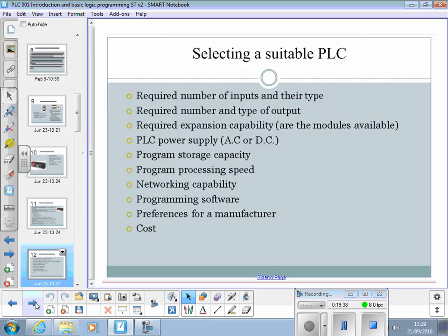You'd be really silly if you counted up 14 inputs and 8 outputs and you went and bought a Mitsubishi PLC with just that number on it, because you're bound to have forgotten something for a start, and someone's bound to come and add something 6 months down the line. So you'd normally go next one up.